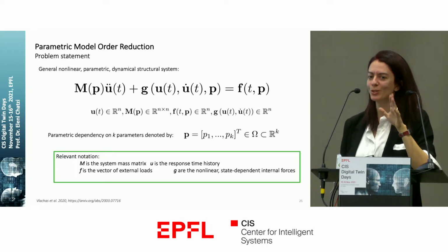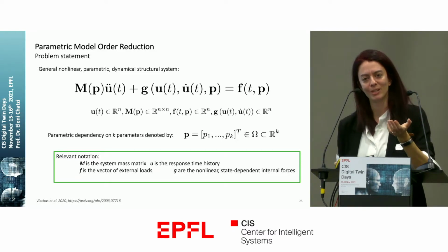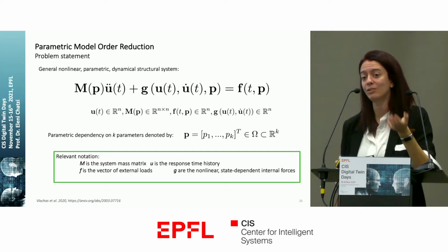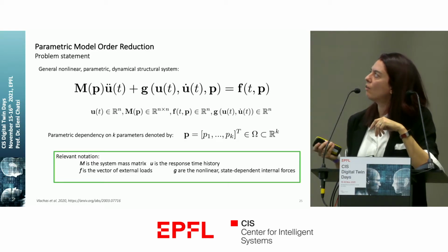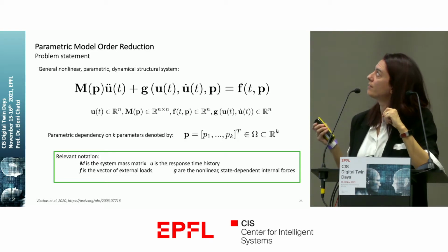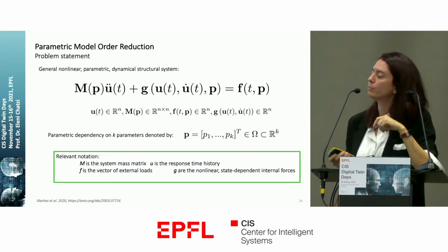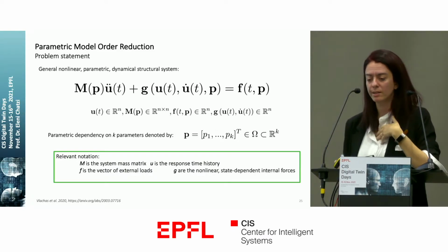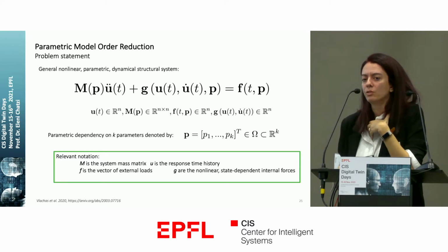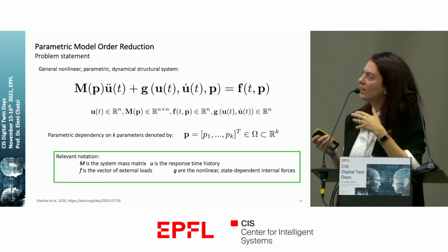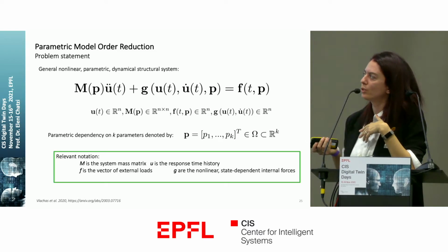So I don't want to just have one finite element model. I want to be able to model a class of systems, maybe systems with different characteristics like stiffness properties, or non-linear properties like yield, or also systems that have a dependence on characteristics of the input. For example, if it is an earthquake, that is particularly relevant for us, on the spectral and amplitude properties of this earthquake. So I would like to have these now parameterized reduced order models.